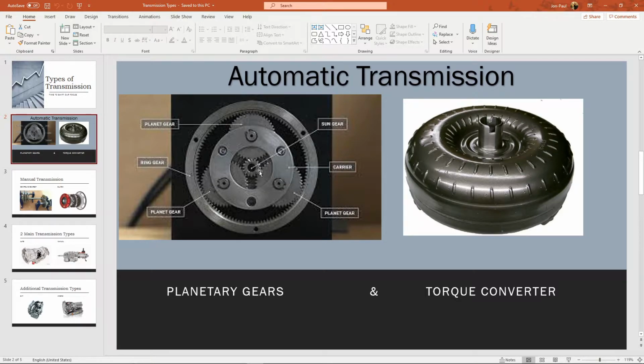In the center, we have a sun gear. Rotating around the sun gear are planet gears. And then the outside is called the ring gear. There's a carrier in here, and the carrier is helping keep these planet gears fixed because I don't want this guy to rotate and then get too close to this guy and bump into that guy. So we're making sure that they all stay equally spaced. So when we talk about these three main components, it will be the sun. I call it the carrier, which is this carrier and its planets, because we're going to use that as one factor in our gear ratio. And then this ring on the outside.